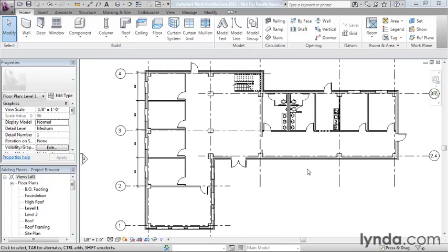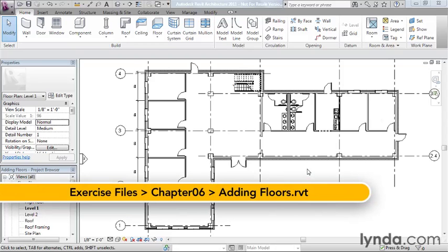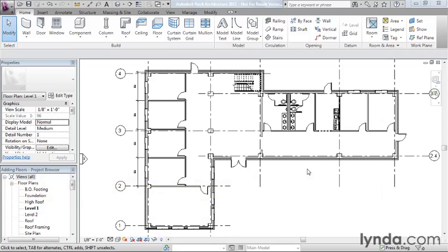Let's move on to sketch-based elements. A sketch-based element is an element that requires a user-defined sketch to show Revit the shape of the element you wish to create. In other words, there's no reasonable way that Revit can assume the default shape of objects like floors, roofs, or stairs. We must give Revit some guidance when creating such elements by sketching out the overall shape of the element. Sketches are two-dimensional, simplified renditions of the element you're creating, and in this movie we're going to look at the floor element as our first example.